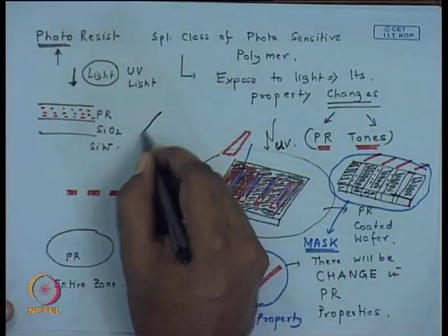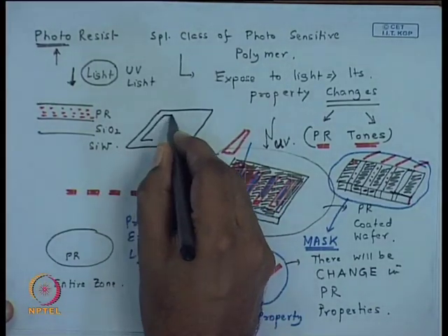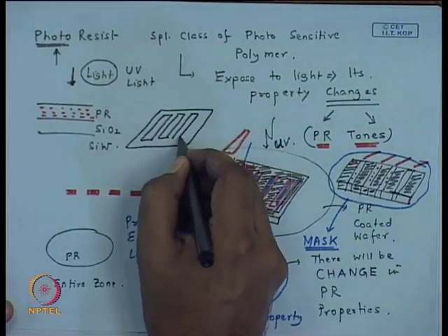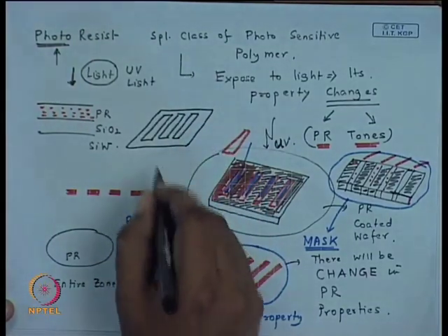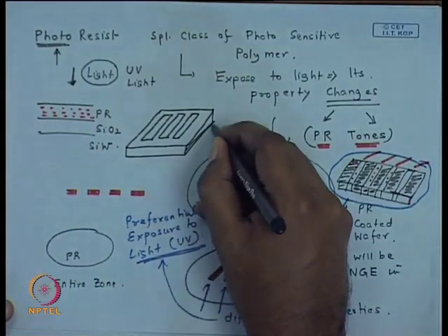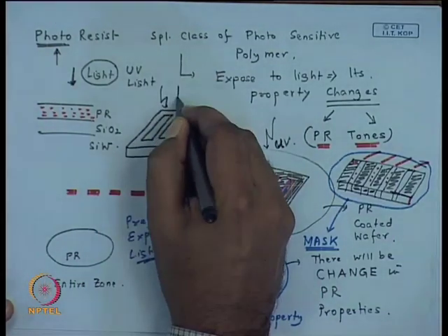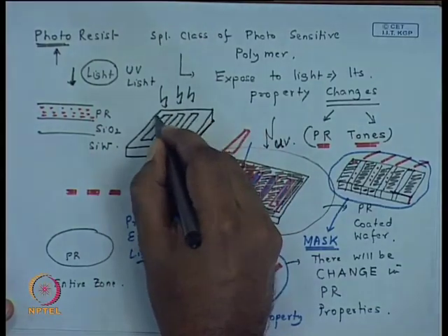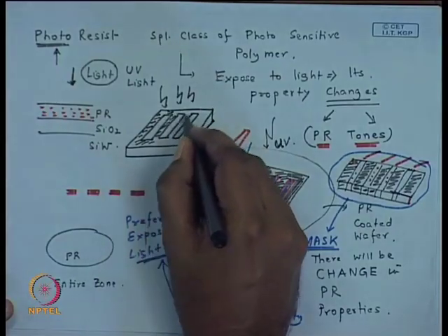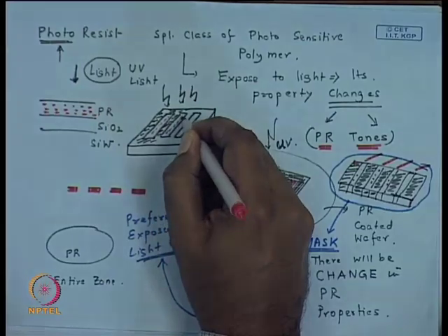So, you essentially have a piece or a flat object which has some slits which allow the light to pass. So, this is the design. So, first the mask has to be fabricated, and then you place this mask on a photoresist coated wafer, and you shine light over it. All these areas absorb the light, they do not allow the light to pass. Only these areas, the so called slits, allow the light to pass.